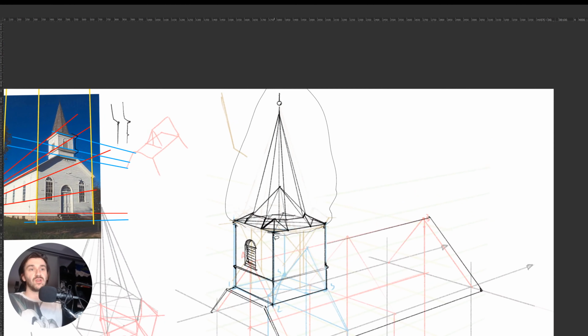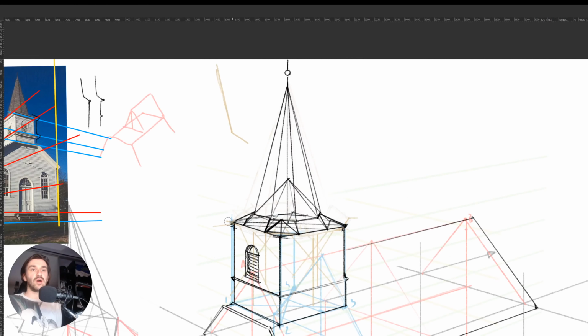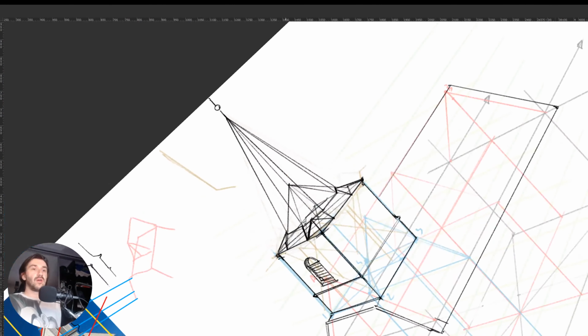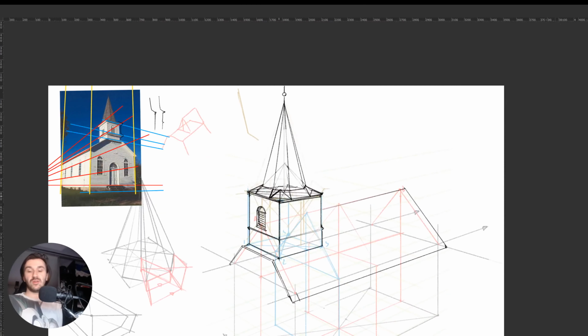And now if I want to create the offset for the thing, I will slightly enlarge it. So the whole rooftop will slightly go out of the outline of the building. And now I will also include some phasing to it, so it will look a little bit more like a developed shape. And let me quickly clean the lines that I don't want to appear in here. And this is how you can quickly change a rooftop.